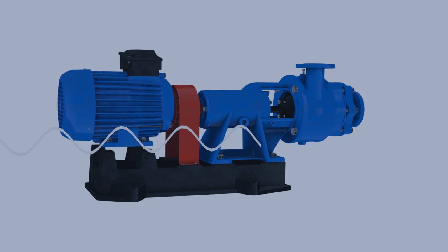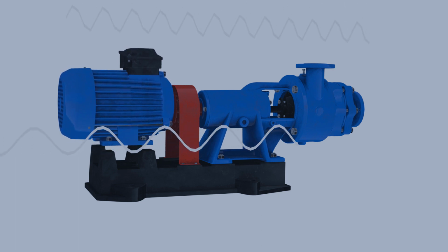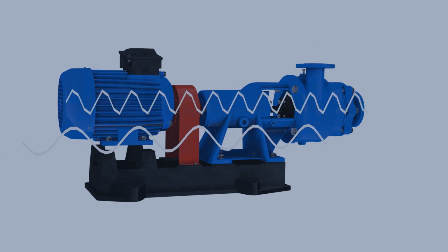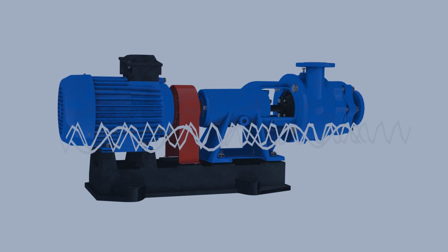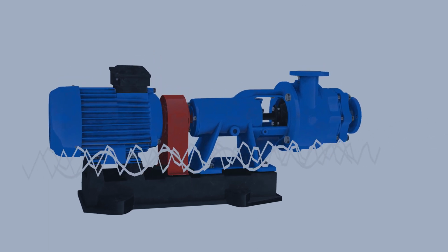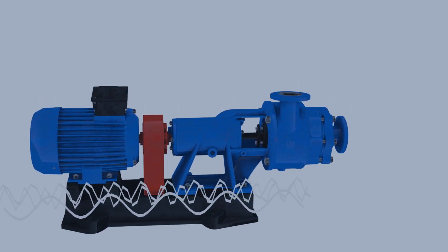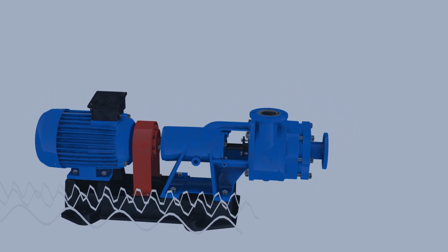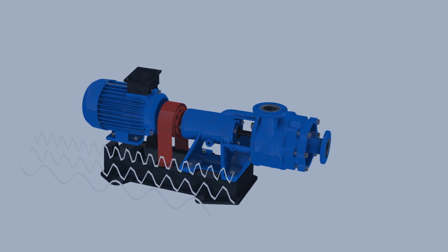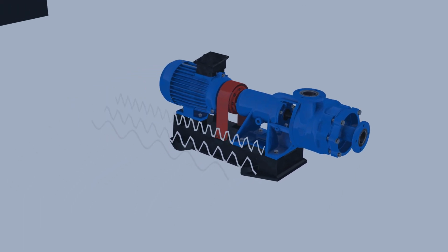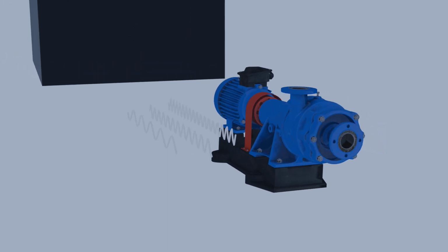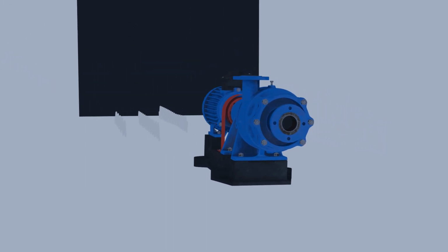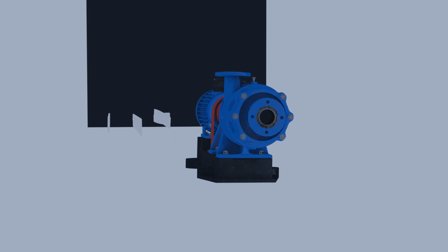On a more complex machine, you can see that the sine wave produced is anything but simple, and would be difficult to analyze. Unless we were to separate out the individual frequencies and represent them as their own function on a different kind of graph. This is where the FFT comes into play. By sorting out individual frequencies, we can easily identify each source of vibration and see its individual effect on the overall vibration of the machine.